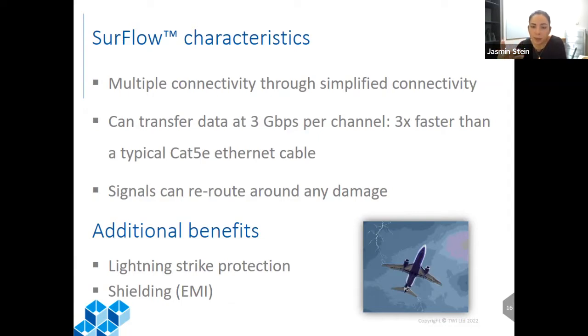So far, we have used a thermally sprayed aluminum layer, and that can be used either as lightning strike protection or for EMI shielding, depending on the requirement. This is more applicable, of course, for aerospace, but if there are certain shielding requirements, even for the car, that can be used in that aspect.